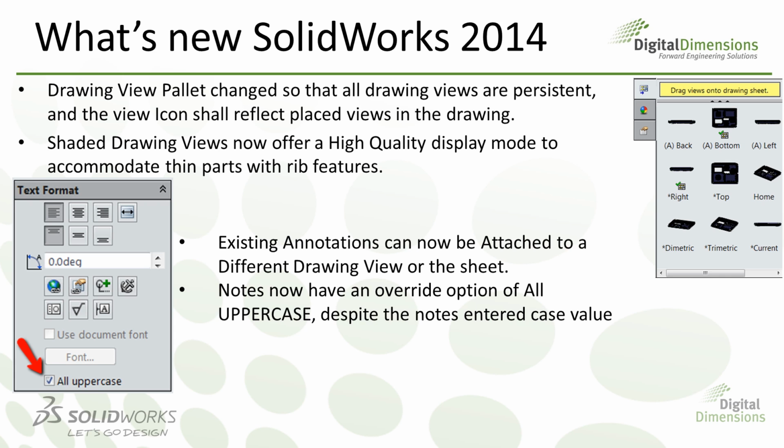In addition to that, we can now set under Tools Options for the document properties, so this would be a template setting, the ability to enforce all uppercase on your notes. This might create an issue such as mm for millimeters on units, in which case it also offers an exclusion area that you can type in the items for it to ignore when enforcing this all uppercase rule.